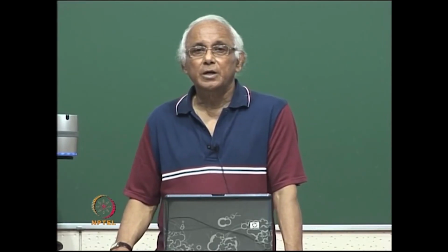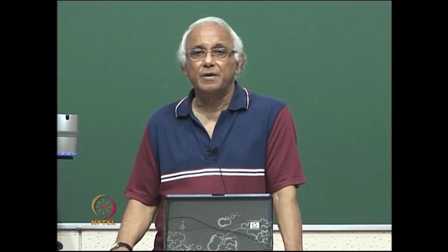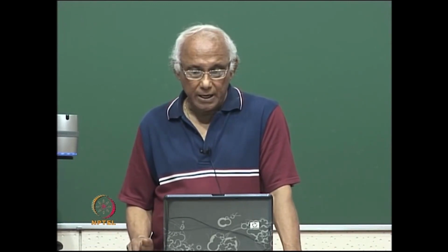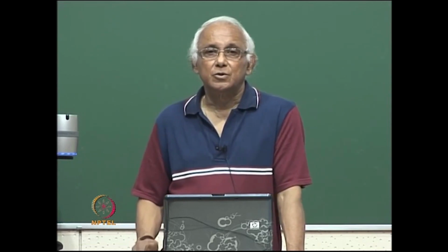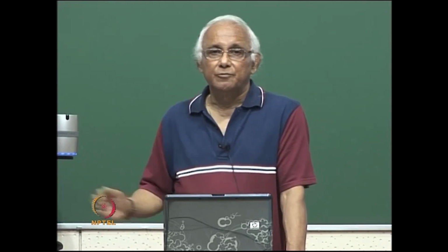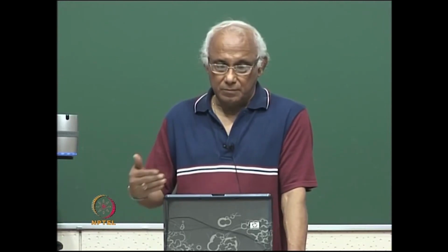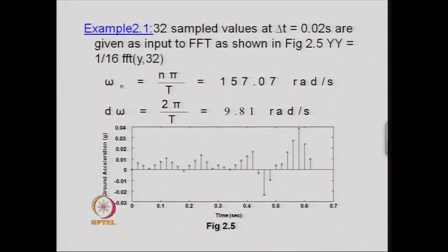Therefore, we consider the FFT only up to a frequency of omega n, not the total frequency range that we get in the X(i omega) plot.